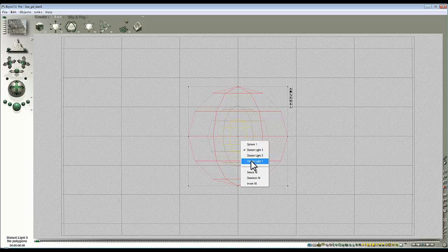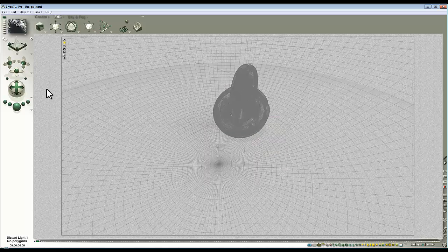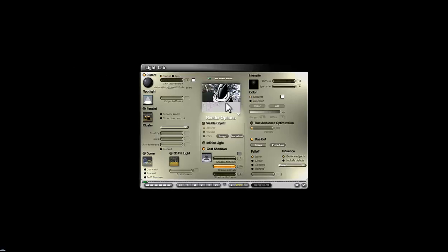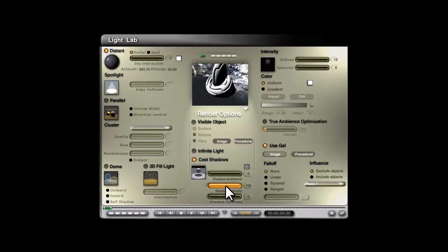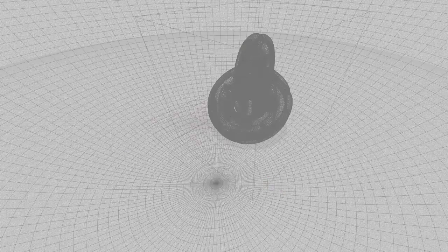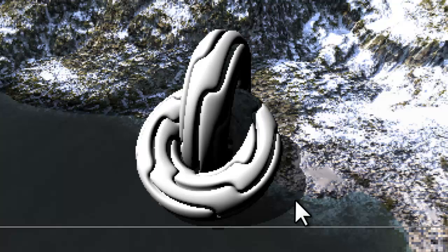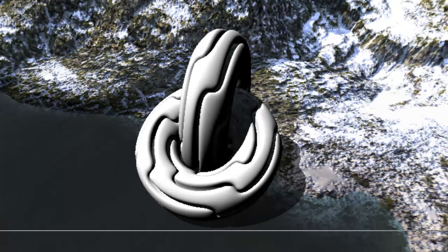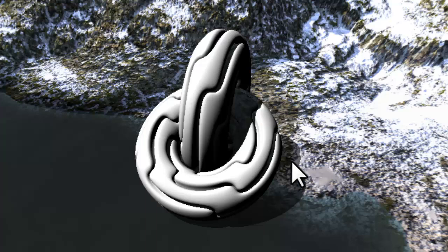source. So if we go to the first light source here, for example, well, another thing to consider before I get onto this just final little bit is if you turn the shadow intensity down, it'll look like a bit of light's getting around from the environment to other places. So if I turn that down to 35, just see the effect of that in the shadow region there, then you can see a bit of the ground. Obviously, because this is being projected onto a flat surface, the shadows can't respond to the changes in the geometry of the terrain. It's just an illusion.